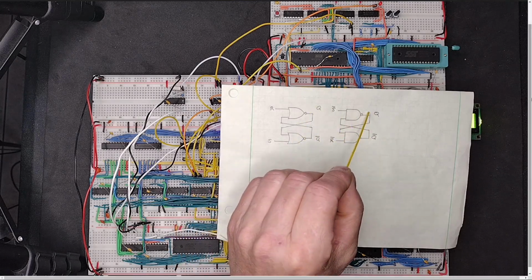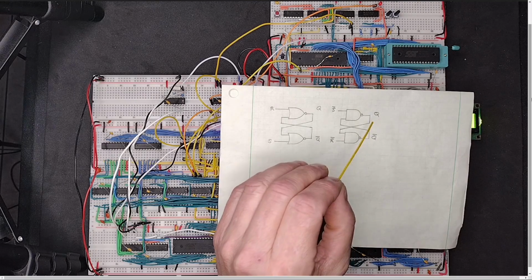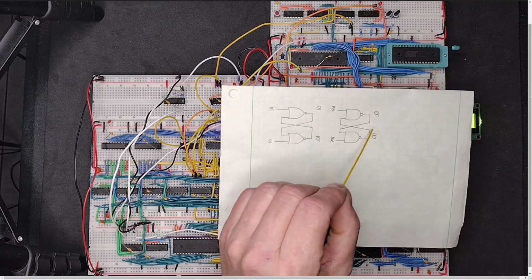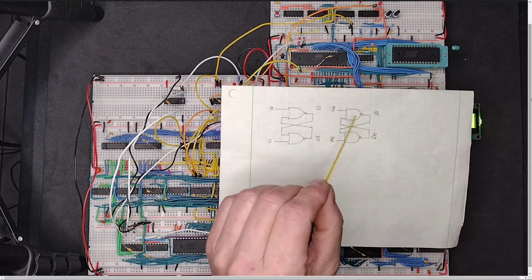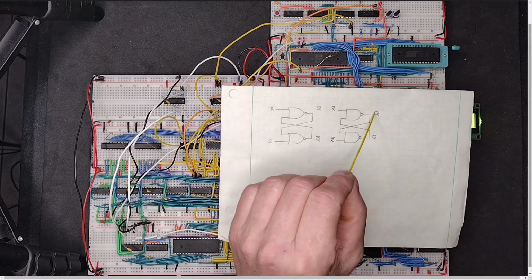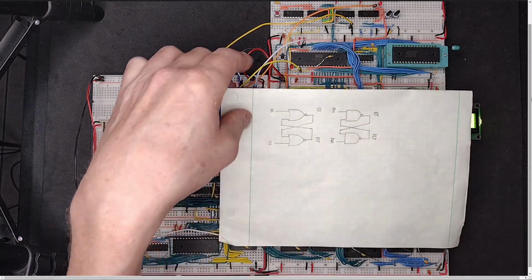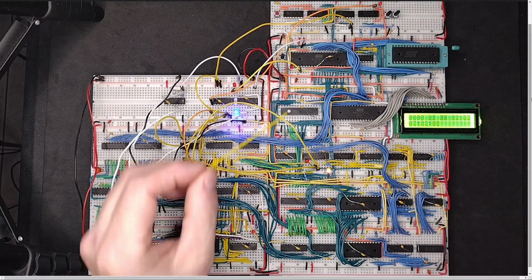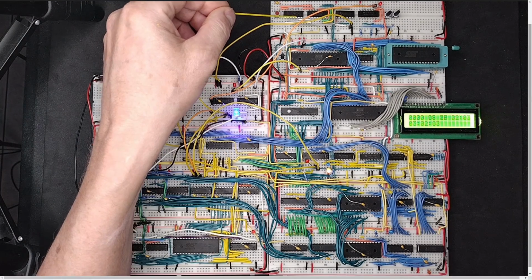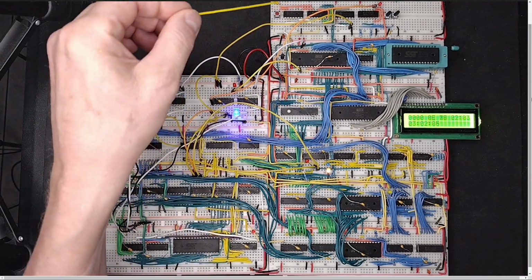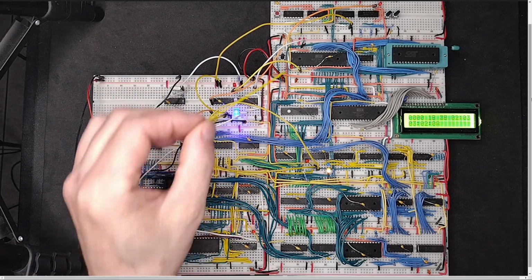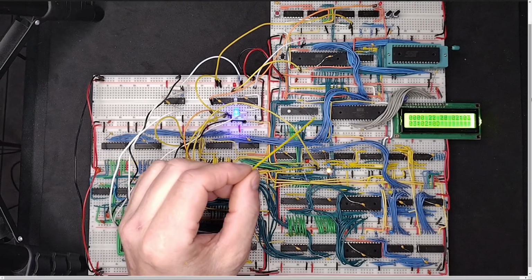In other words, if you considered Q to be true when it's negative, then this would be the Q prime output and this would be the Q output. But we're not using it that way. We're just going to use it in the normal way where we want a Q high signal. Now, I have an additional complication with my system. Because I have this single-step debugger board, I also need it so that when the computer is in debugger mode, it's not going to handle interrupts, because the interrupts would get in the way of being able to single step in the computer.